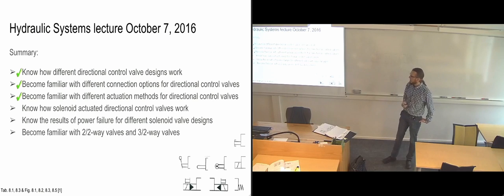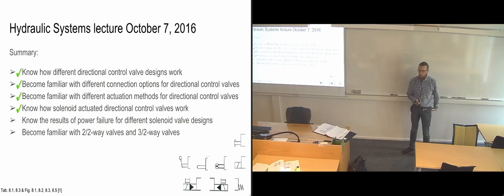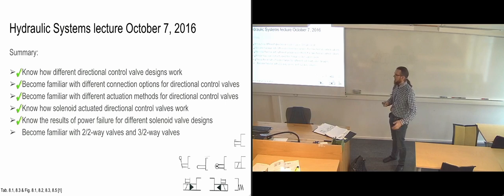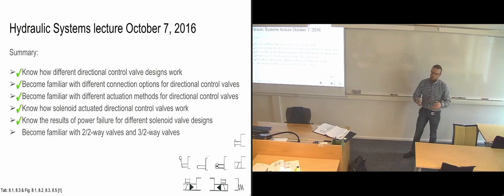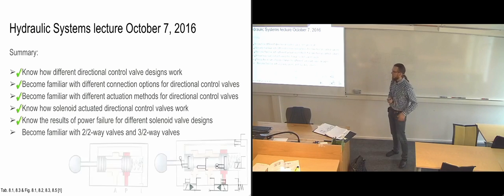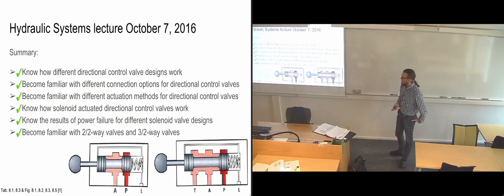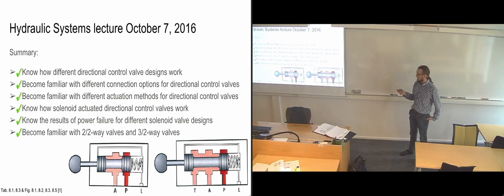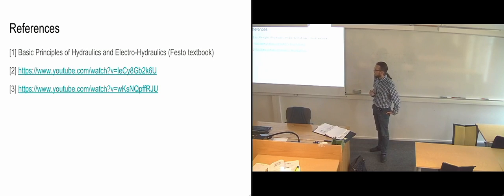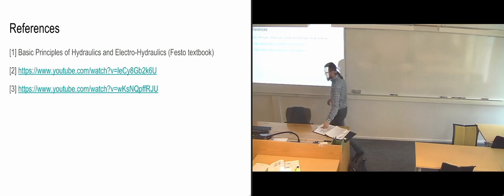We also looked at how the solenoid actuation works. And we've also looked at the results of a power failure or a wire break in the solenoid. So how can you design your solenoid to act the way you want if you lose electrical power to it? And then we've looked at 2 two-way valves and 3 two-way valves on this one. And we had 2 YouTube clips that we saw on Friday.